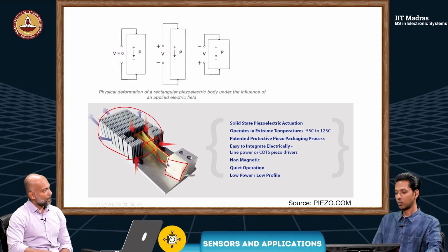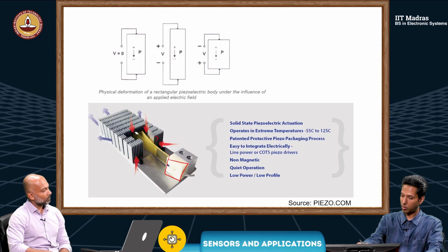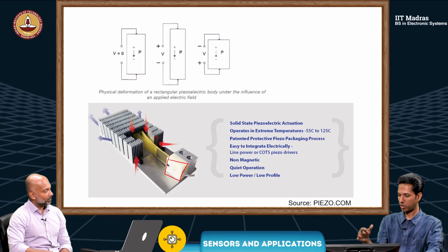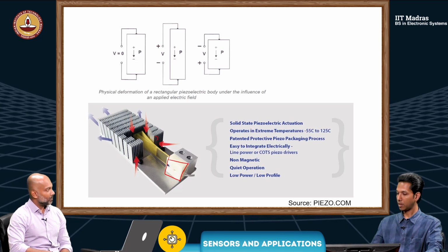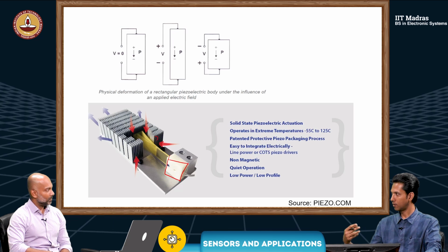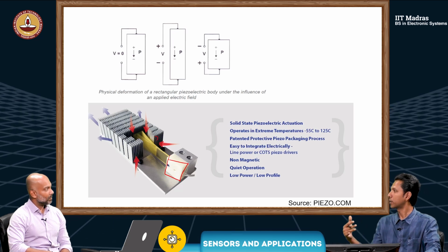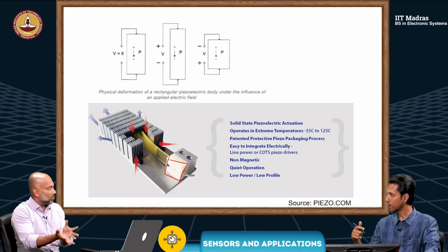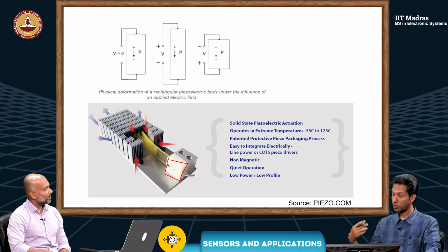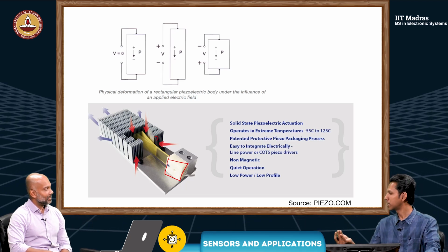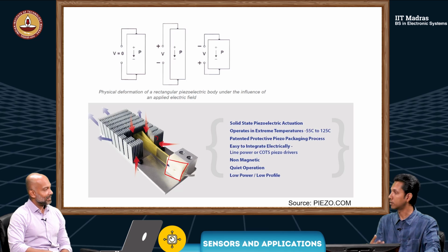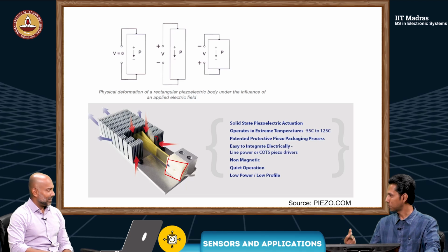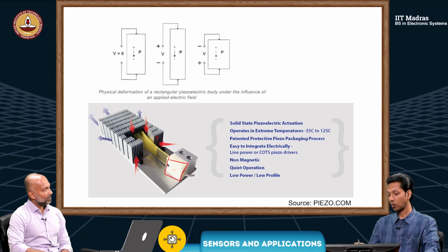Let's say this strip is available and exposed to some kind of vibration. Then there will be voltage generated, an energy conversion from mechanical to electrical. It could be stored somewhere and then used, for powering small sensors and so on. Of course, it will not generate huge amounts of voltage or watts. It will generate some microwatts. But we don't need watts, right?